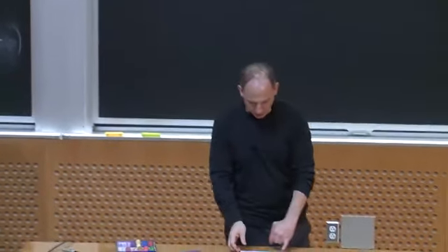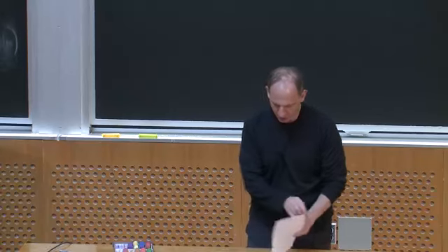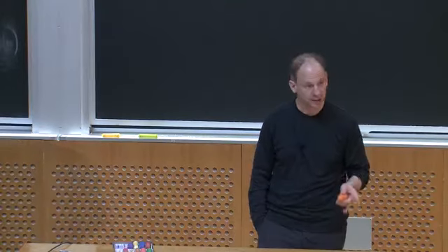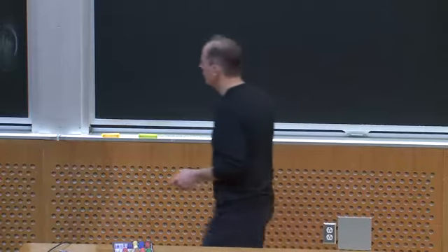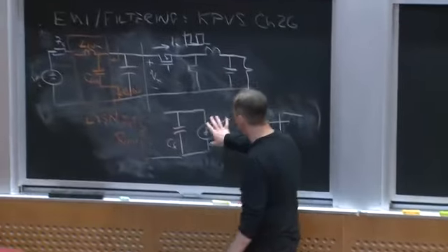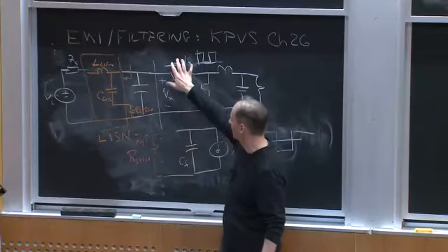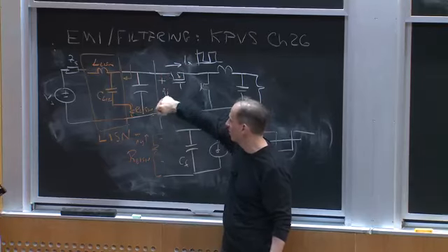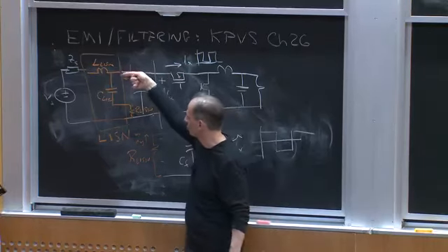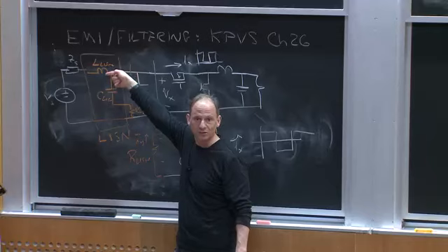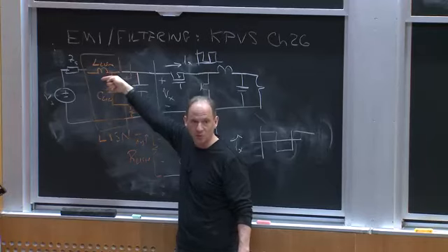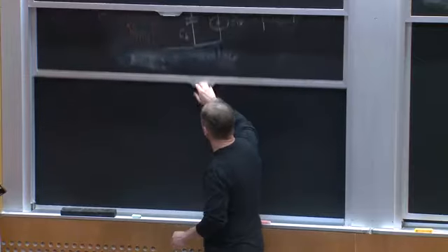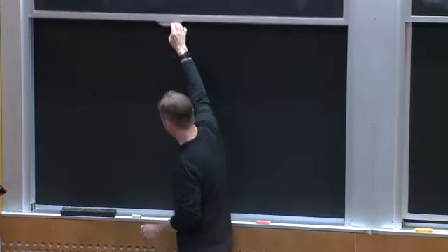So we said, okay, we need to design a filter here. A capacitor is not going to cut it because, for typical specifications, who knows what this is, maybe this is tens of amps. Typically, the current I'm allowed to squirt back into here is on the order of tens of microamps. It's really small, okay? So we usually need to design a higher order filter than that.